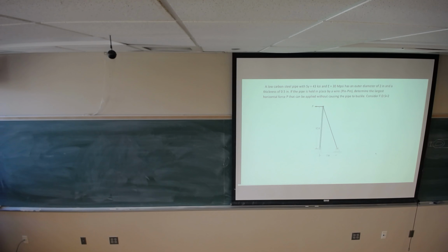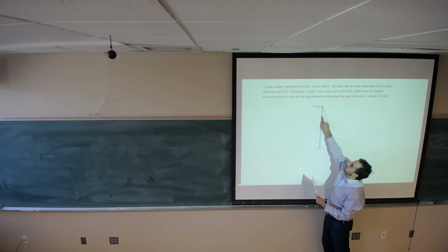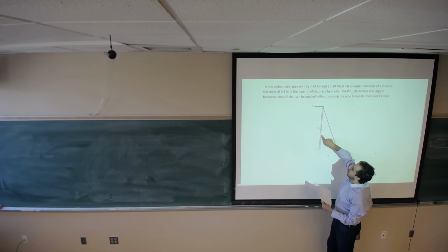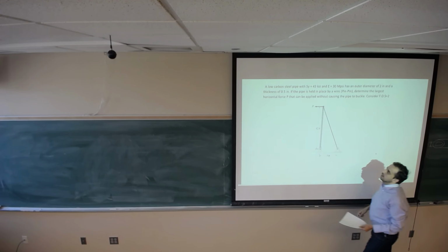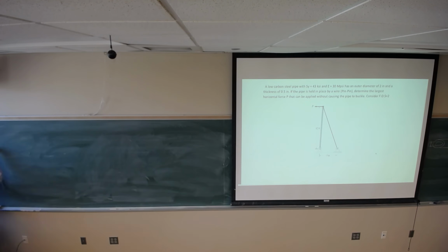So the first thing that we should find from the statics, this force is making force in this pipe and in this cable. What would be the axial force applied to the pipe? So it's going to be one force applied here, force P.